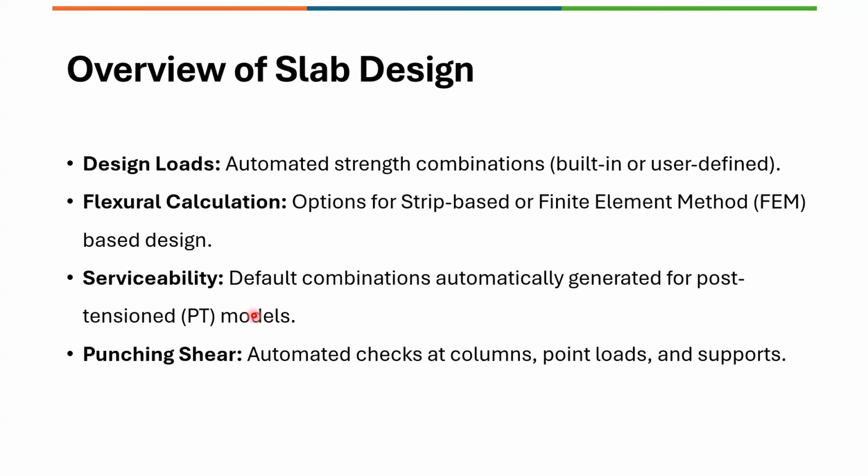So the slab design involves definition of load combinations, which is automated. As you define the load pattern, the program recognizes the type and applies the load factor required, similar to ETABS, and can generate design load combinations based on the code set under the design preferences. Then flexural calculations, and then serviceability for PT, checking the stresses, and then punching shear check.